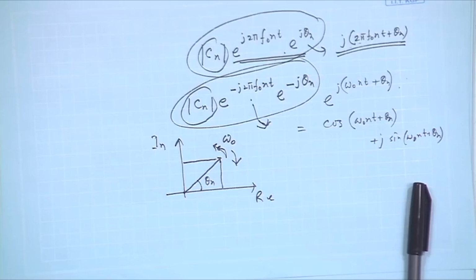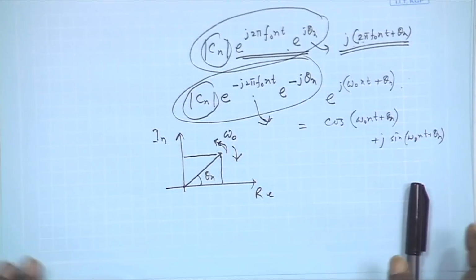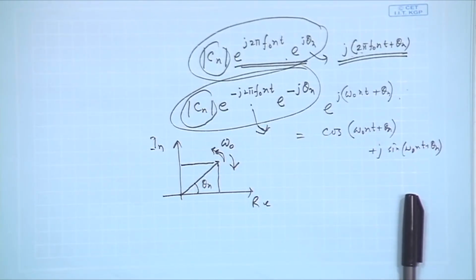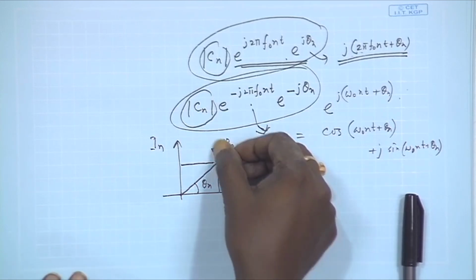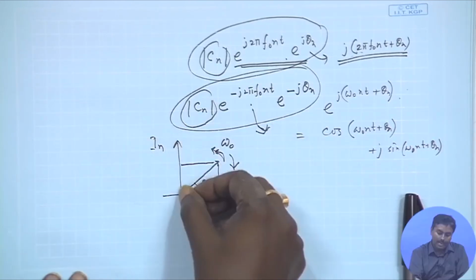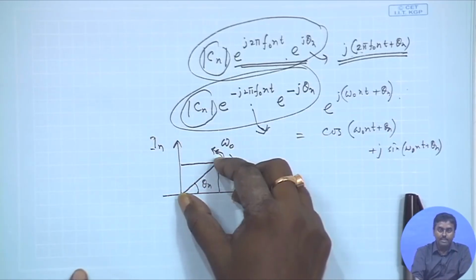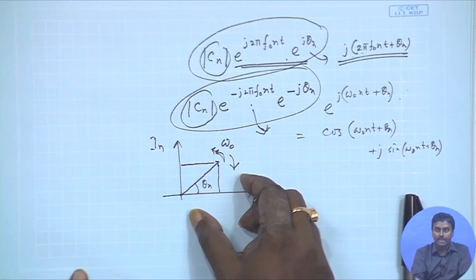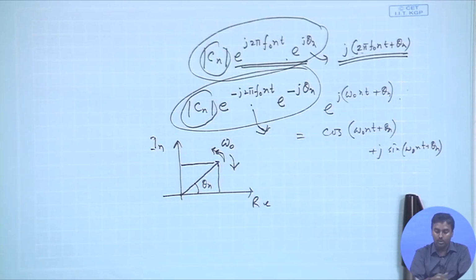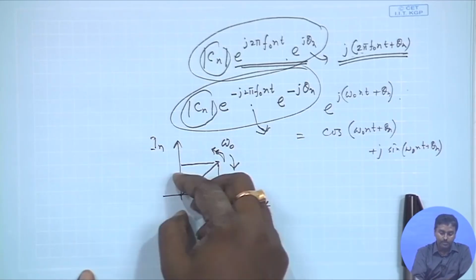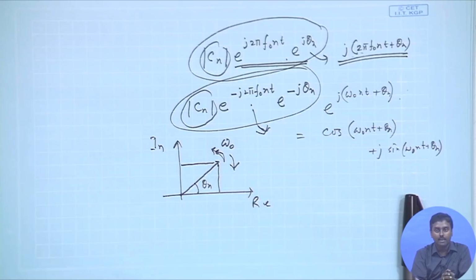And if you see why the signal is becoming real, I have this representation. If you are interested, you can trace the signal of the positive phasor, and the signal of the clockwise rotating phasor, and add these two up with respect to time, taking the values at every time instance.